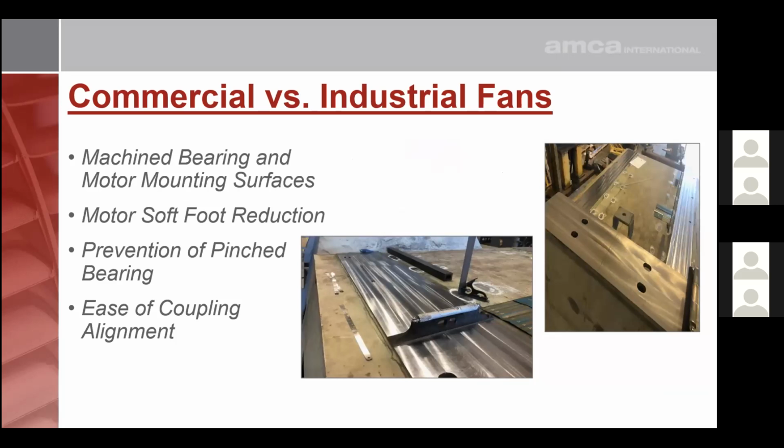One more feature on industrial fans is that they commonly feature machined surfaces for mounting of the fan bearings and motors. You won't necessarily see this on commercial fans. Unlevel mounting surfaces can result in a motor softfoot. A motor softfoot is distortion of the motor frame when it's bolted to an unlevel pedestal or subbase. That distortion of the frame can result in a negative impact on the motor air gap and reduce the motor life.